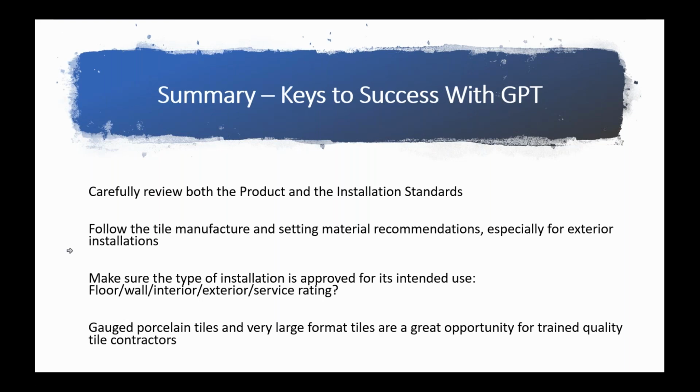Follow the tile and setting material manufacturers' recommendations, especially for exterior installations. Many manufacturers of gauge porcelain tile have a listing of adhesives in the back for different uses, whether it's interior, exterior, walls, floors, size of the tile, etc. And they reach out to us as setting material manufacturers, and usually a variety of different ones.